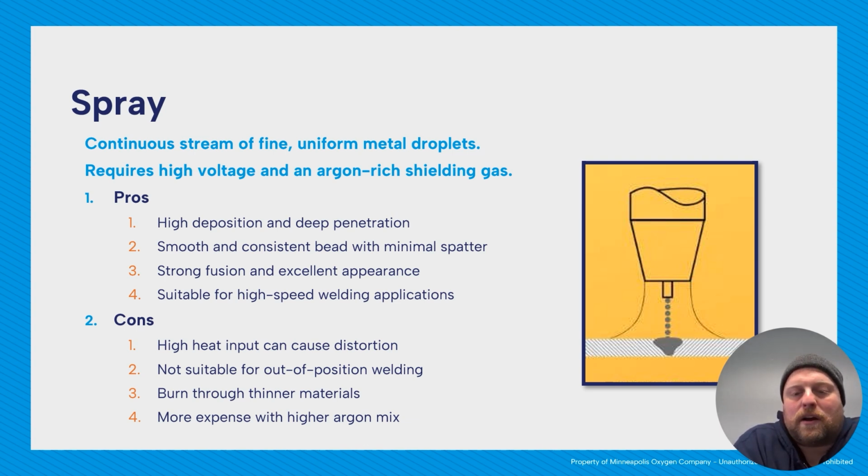The cons are tons of heat, so it can cause distortion. You can't do it out of position because you need gravity to help get those droplets where they need to be. And also it's just so hot, it can't coalesce fast enough, so it kind of just drops out. You'll burn through thinner materials for sure. And then you have more expense usually because you have more argon in your mix.